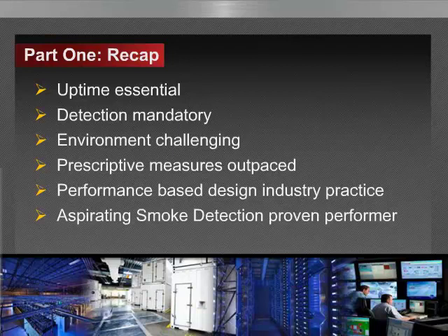And given the dynamic environmental and operational characteristics of mission-critical facilities, meeting detection objectives can be challenging. So consider factors such as magnitude and direction of airflow, the circulation modes of temperature, equipment cabinet layout, concealed and enclosed spaces, and overall room geometry.